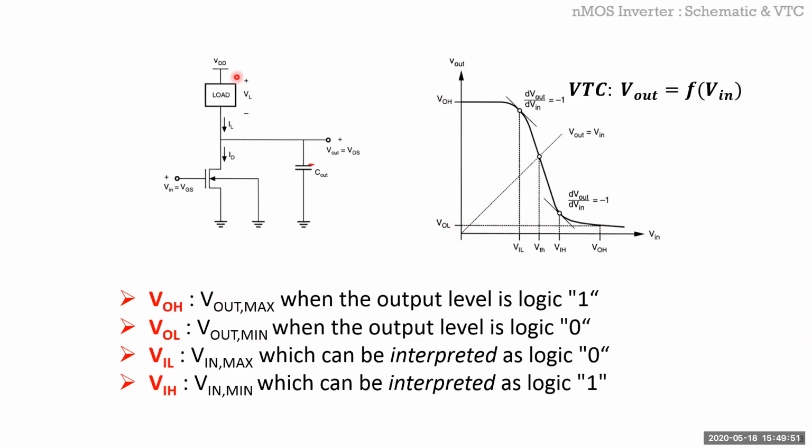Again, in this CMOS case, ideally you want this to be ground because you just want to utilize the entire spectrum of your supply voltage. Not only that, you want to maximize your noise margins, which I'll talk about in detail in the coming few slides. So that's your VOL. What is your minimum output voltage for logic 0? Minimum you want it ground, but it may not be the case depending on the architecture of your inverter or your logic gate.